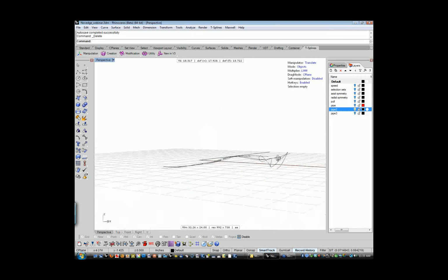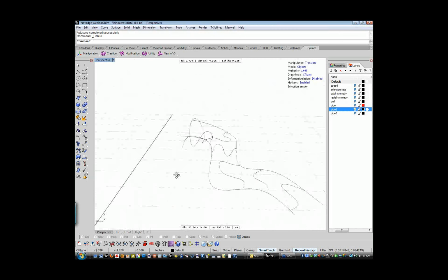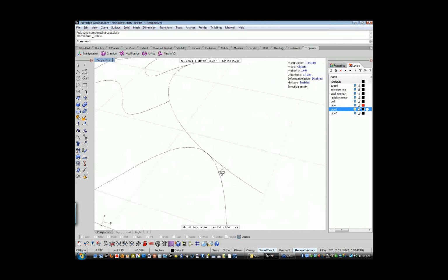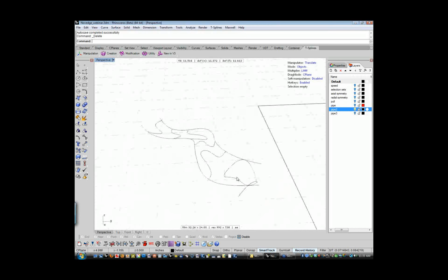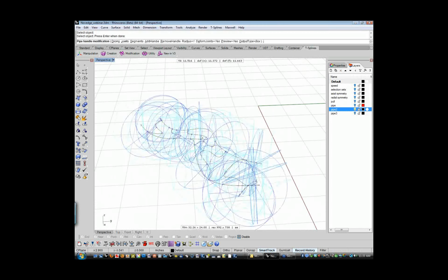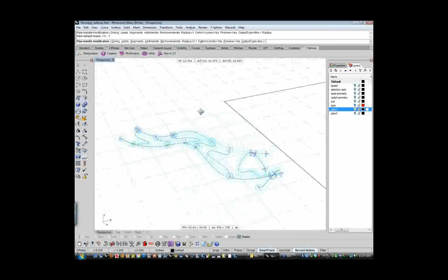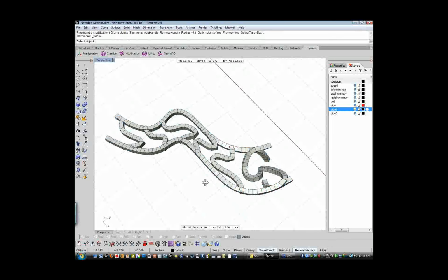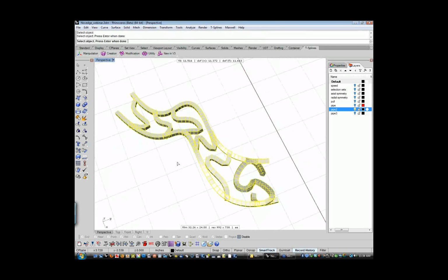So, more Rhino curves. I just have them thrown in space, and they're also fairly disorganized. They are all touching, but I also wanted to show that in this case, they're coincident at this intersection, but they're not trimmed. So I can run the pipe command again, and I got to change my radius. And if I just accept this as is, just to demonstrate the point, you'll notice that it goes and builds my box preview.